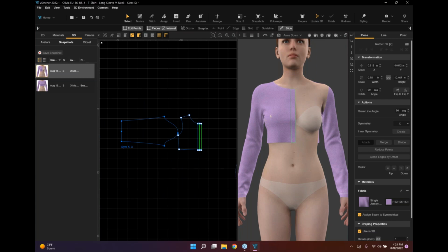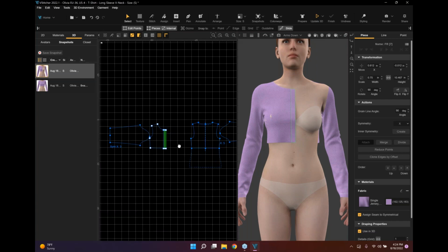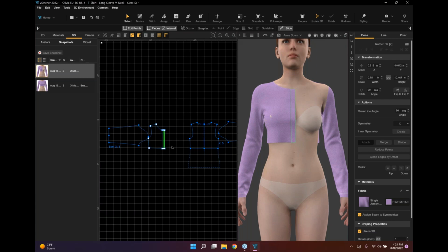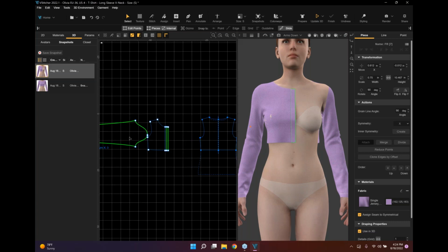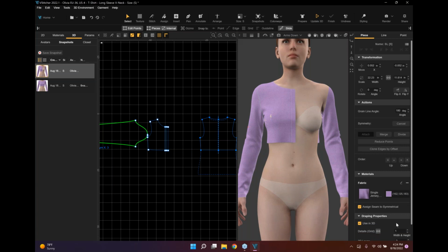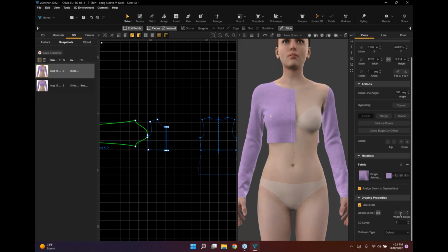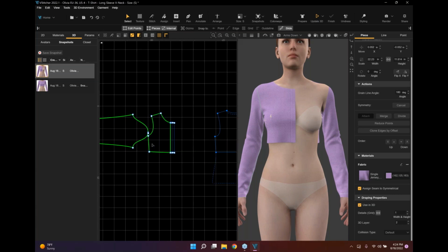Another thing you want to make sure is that all of your grids are updated. If your garment looks okay with the grid of 1, all of the default grids are set to 1, then it's okay to keep it that way. But if you want it to drape more naturally with the physics that were scanned for this fabric, you might want to adjust this and lower it to about 0.5 or 0.7.